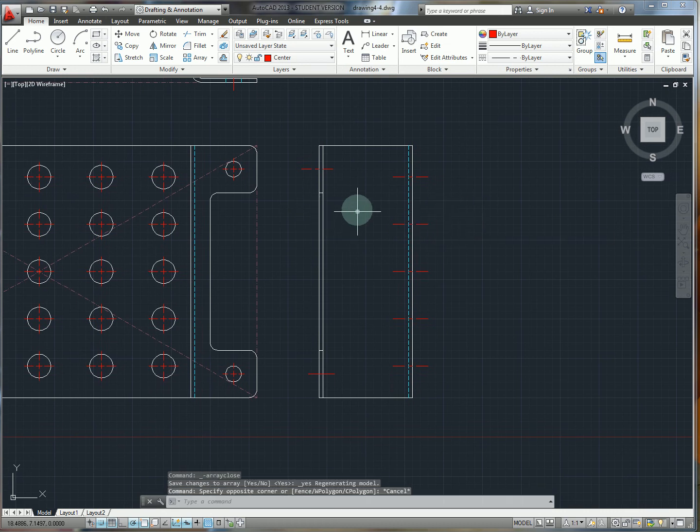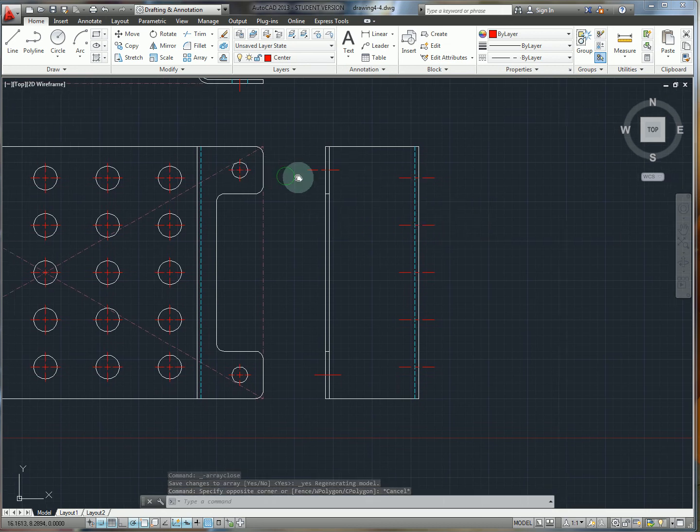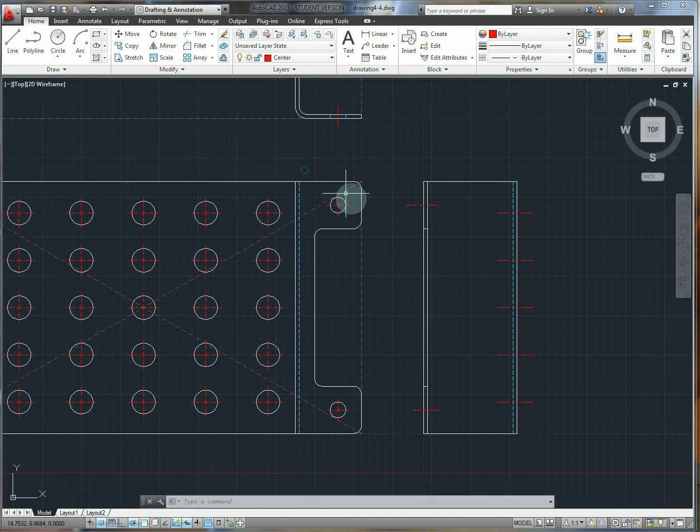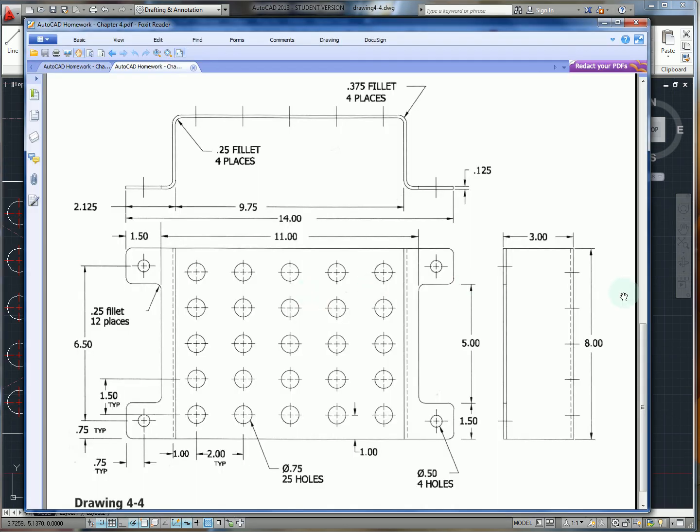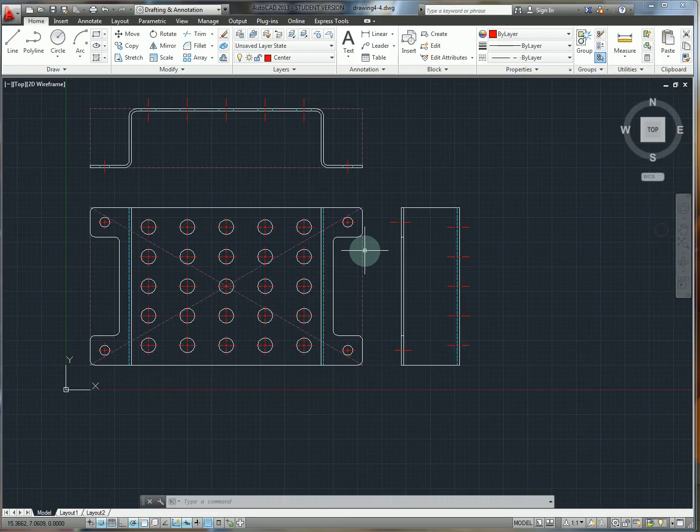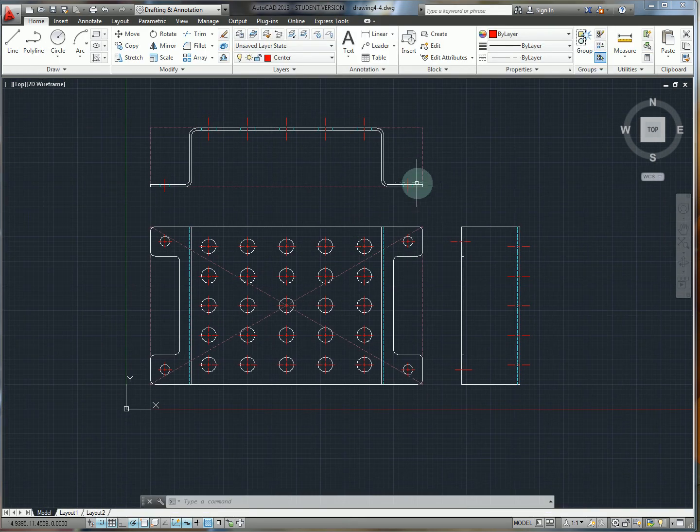So for now, I'm just going to ignore the hidden lines corresponding to these circles, since, as we can see, our source drawing kind of omits them. So since it's obvious we're talking about a thin part, we don't necessarily need all the detail there. So at that point, we have our three views, our offset applied to create the sheet metal feature, and a nice side view here.